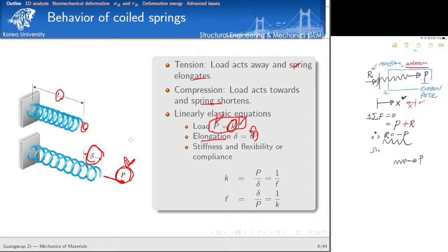Let's consider internal force. What's the sign convention for the internal force? Do you remember the last time I told you that the internal forces are nothing but the stress resultant? That's why the sign conventions also follow that of the stress. That's why if it elongates, this is positive. That's why this is our default internal force. Here the N is internal force. So note here P is this external one.